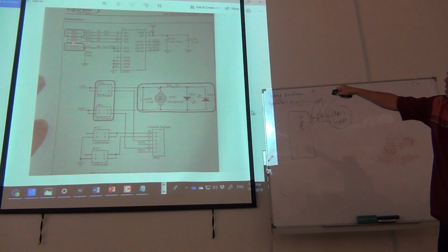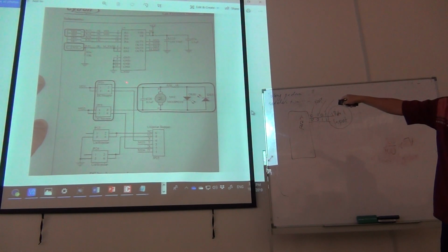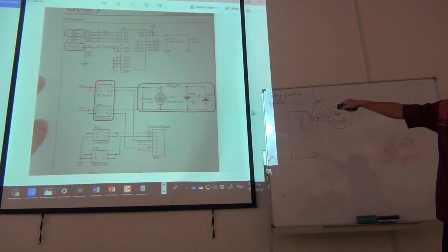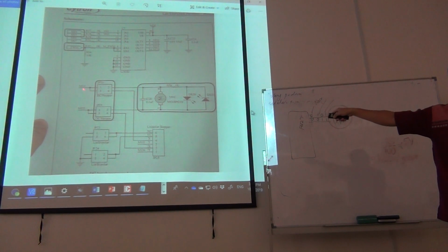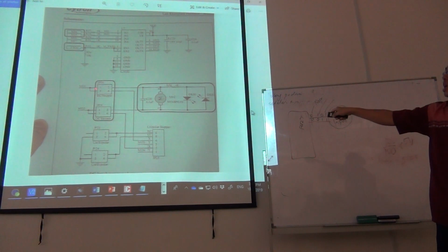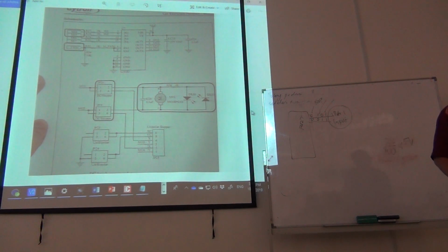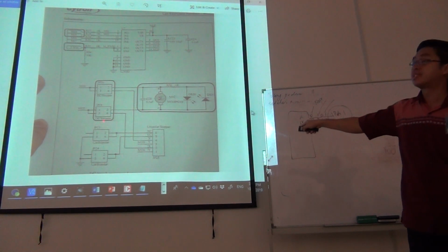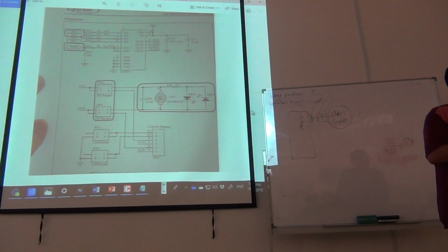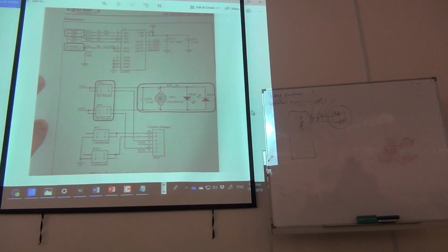Next one. What else do I need to tell you guys? So for you to run a motor, you have to go back to jumper 20. Jumper 20 is on the board. So you have to set pins 1 and 2 to jump for the motor. If you jump 3 and 4, sorry, they will go for the stepper motor over there. So on the board, they have stepper and they have DC motor. It's sharing together. So choose the DC motor to play around.